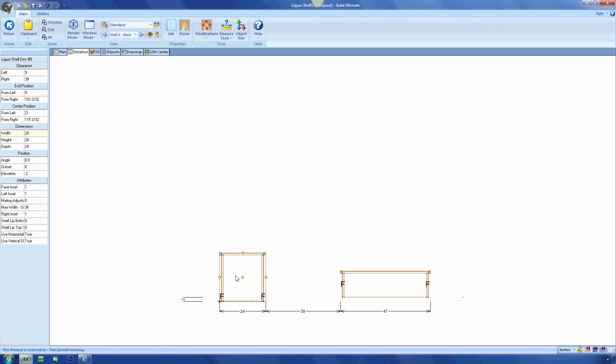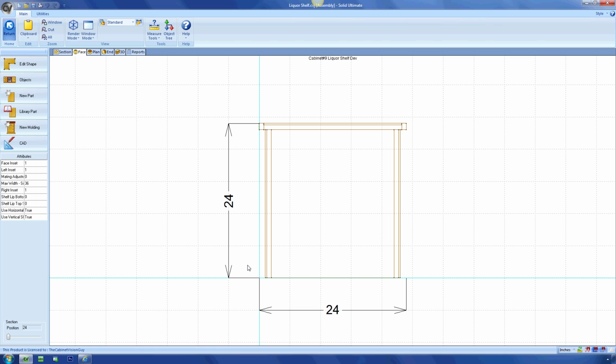You can immediately see that I have more than 3 parameters here. Let's go to the assembly level so that I can explain what these different parameters do. First, we have the use vertical skins parameter, which I can set to true or false. True makes the left, right, and face skins appear in our views and cut lists, while false removes them. Then, of course, I made one for the horizontal skin, the one here on top that we used for the shelf.